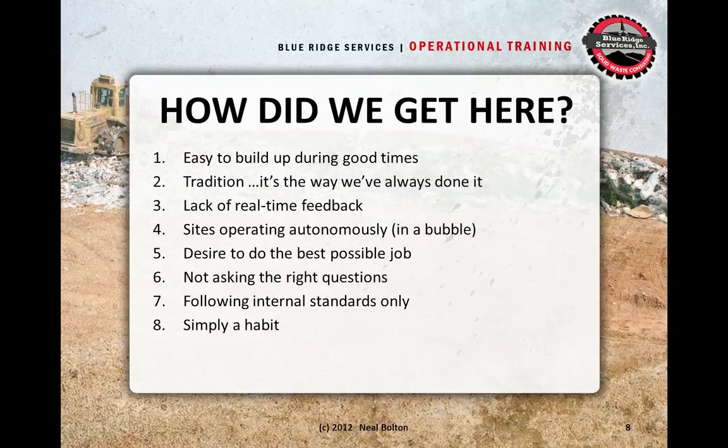And so we may find that when we fly the site, we have a 3-to-1 cover ratio. If you're in the landfill business, you know that's pretty typical. But what that doesn't show us is the performance day to day in terms of where we are. And what we'll find when we look at detailed information is that there's a lot of variation out there. So lack of real-time feedback really doesn't let us pinpoint where we are doing well and where we aren't.